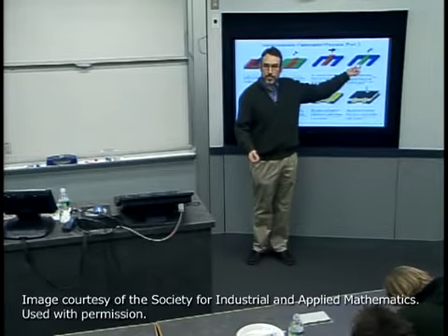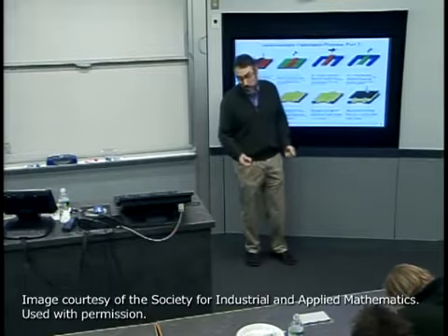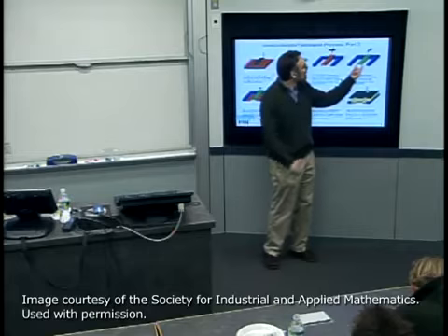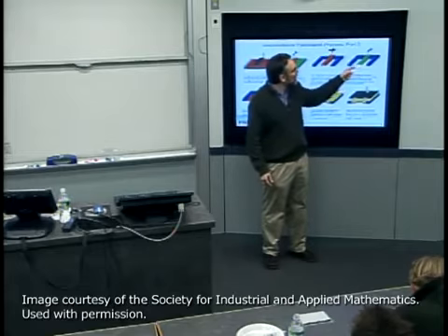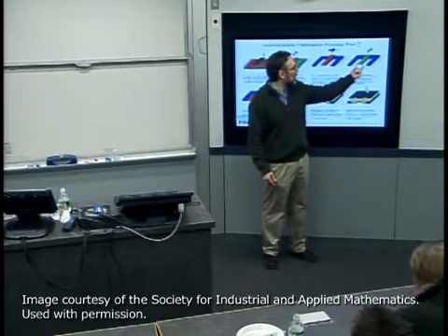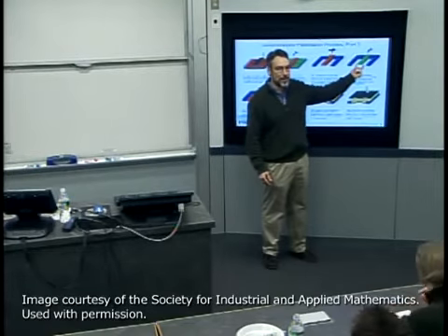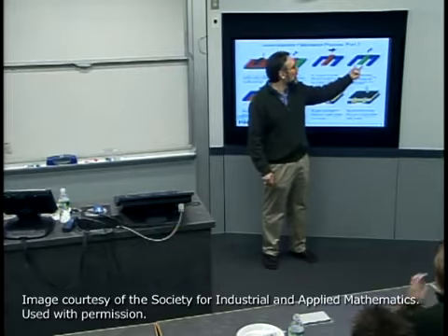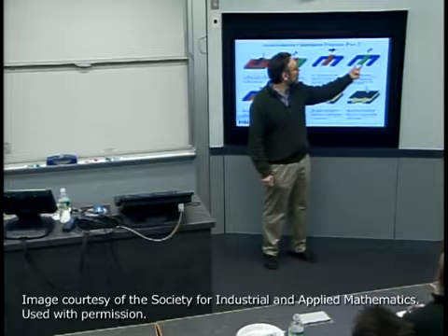of the transistor. You can sort of think of it as, and we're actually getting closer in the dimensions that we're talking about now, that the time of flight of an electron underneath that electrode will depend on the width or the length that it needs to transit. We're getting close to these velocity limited transport regimes.